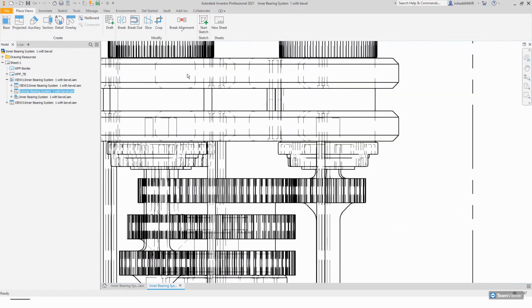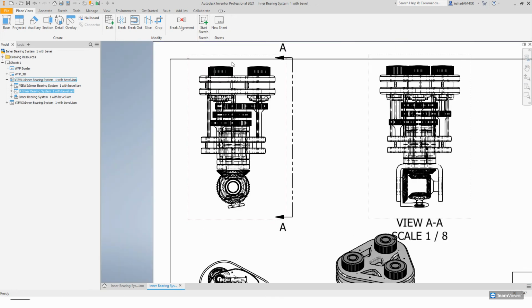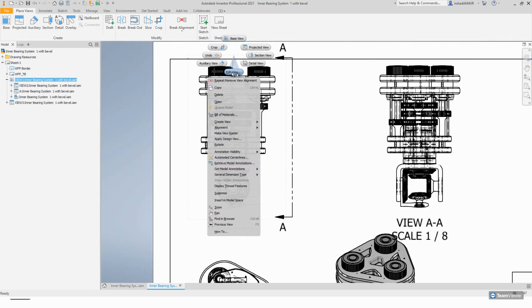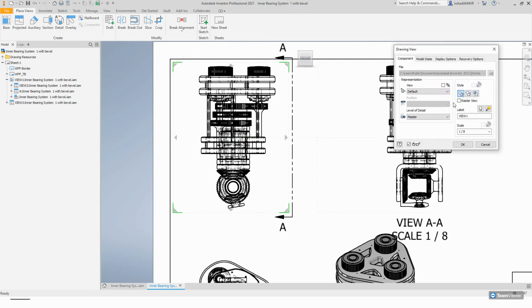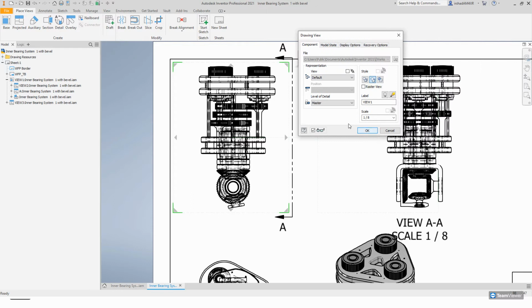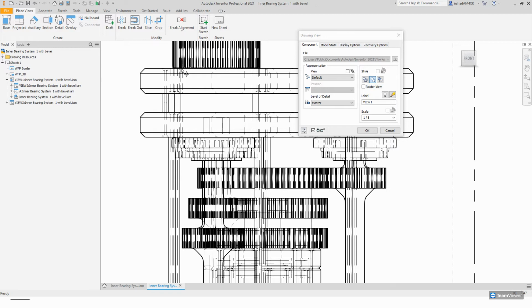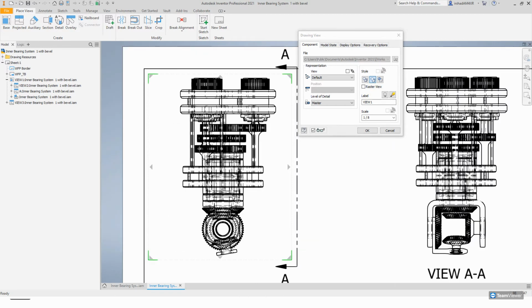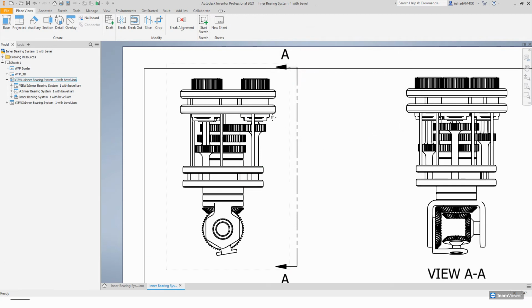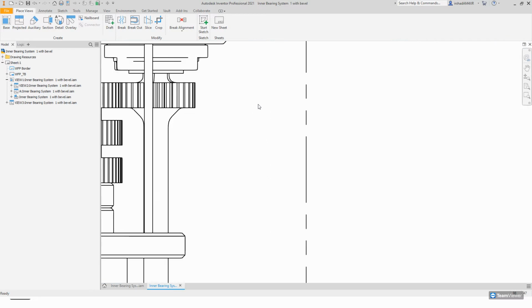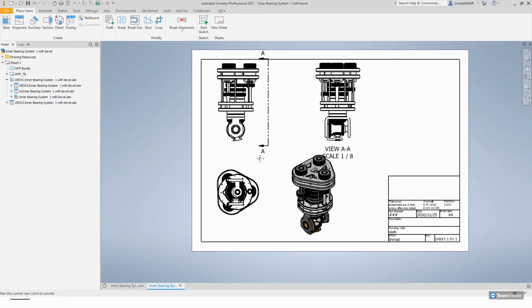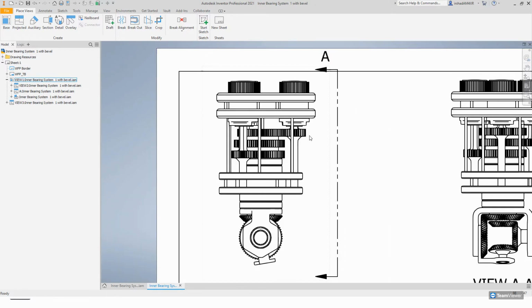Okay. Now you'll notice that I've chosen to include the hidden lines in here. I've also got the option to remove the hidden lines, but these don't look too good because, well, the dashes are too big. And I'll show you exactly how to change those hidden lines to be maybe light gray solid lines. I prefer that, so we can always take a look at it like so. As is, these are just the hidden line removed views, so you won't see whatever's behind the diagram here.